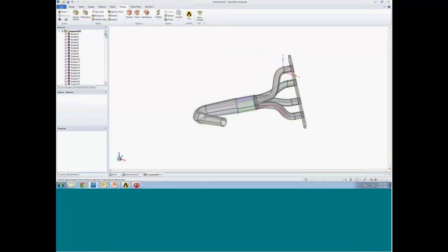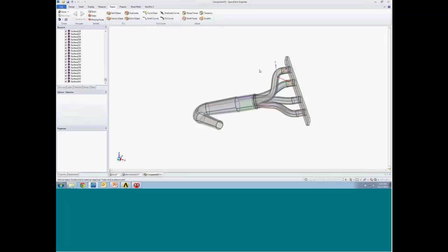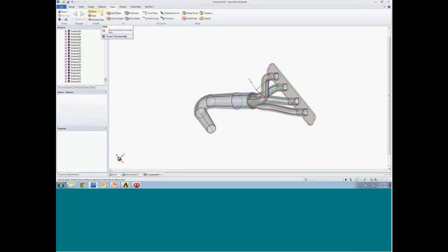So it's easy to open up models separately. You'll see there's 244 surface bodies in the model. Well, that's a dead giveaway to me that I need to use my repair tools, and namely ones that will attempt to solidify this model. Now, these are all automated tools. SCDM will walk you through the process of what to do in attempting to stitch bodies together, stitch surfaces together. If you have a watertight collection of surfaces, it'll form a solid right there.